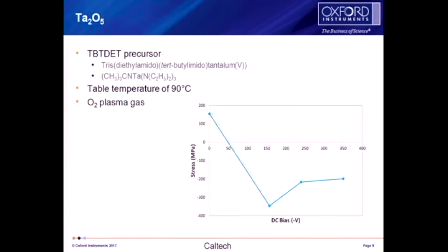Not being that familiar with stress control in ALD, what are other methods that people have explored that you're aware of for stress control in ALD? Besides the plasma enhanced RF? So, sorry, are there other methods of characterizing? No, of producing, of controlling it. I'm not aware of any others. Okay. Classical one, you change pressure, so you change the ion energy to the surface. But the ion energy to the surface is so low in ALD, anyway, you're not going to change it by very much.